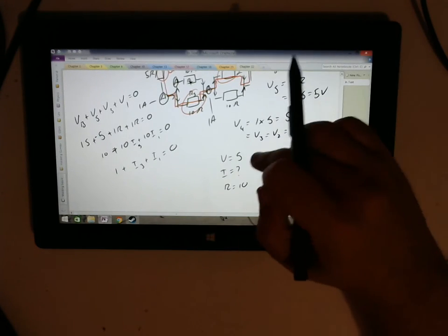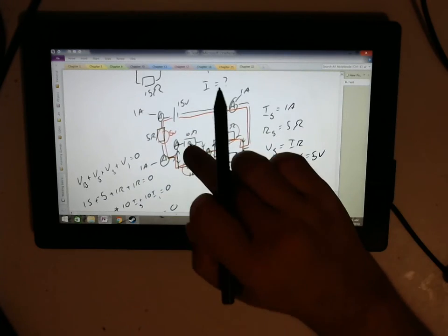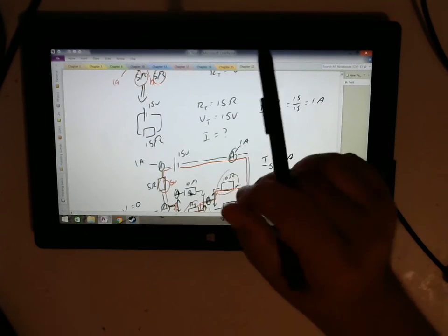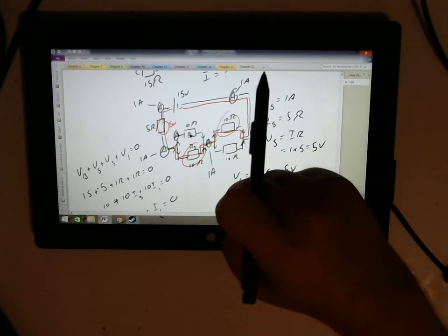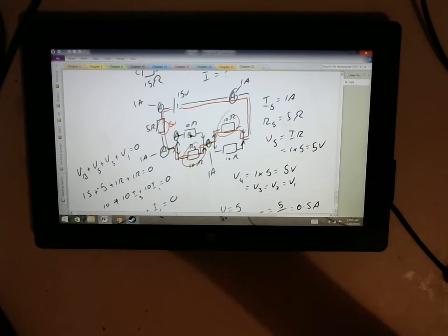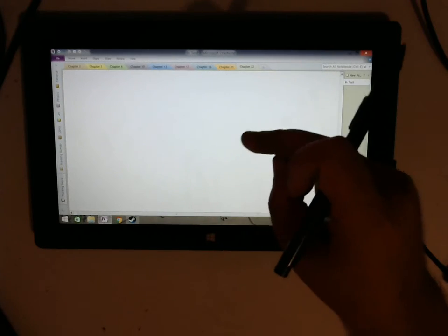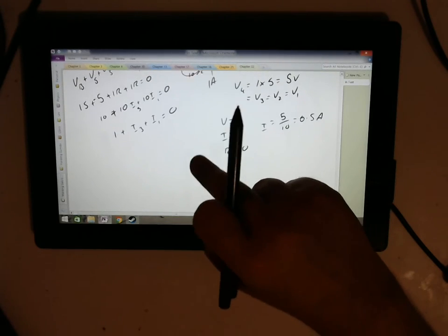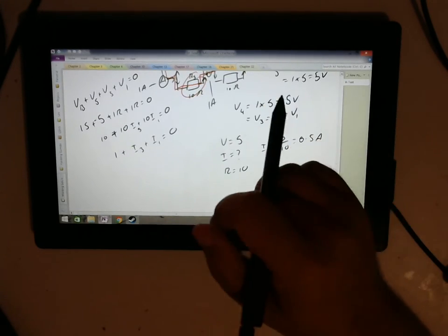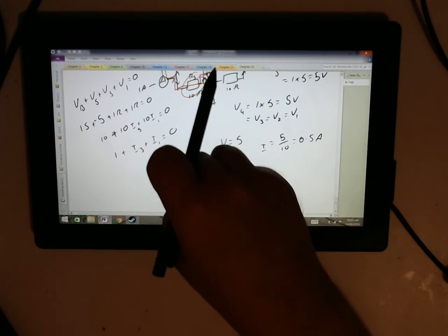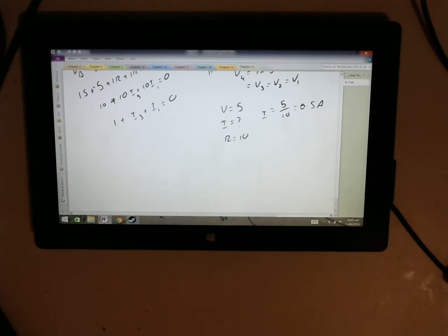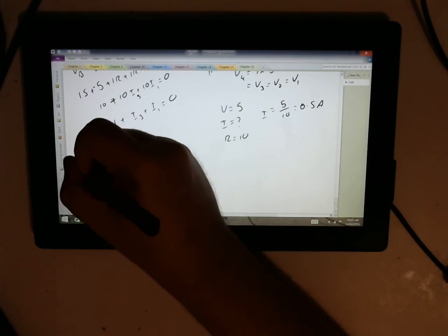Focus on what we did there in terms of that intuition and using our equivalent circuits to work out the voltage. Remember that voltages in parallel are always the same, okay? Which would let us say that V4 equals V3, and so there's some more equations that we could use. As I said, very, very annoying. Okay, we're making pretty decent time. Let's move on to question 13.